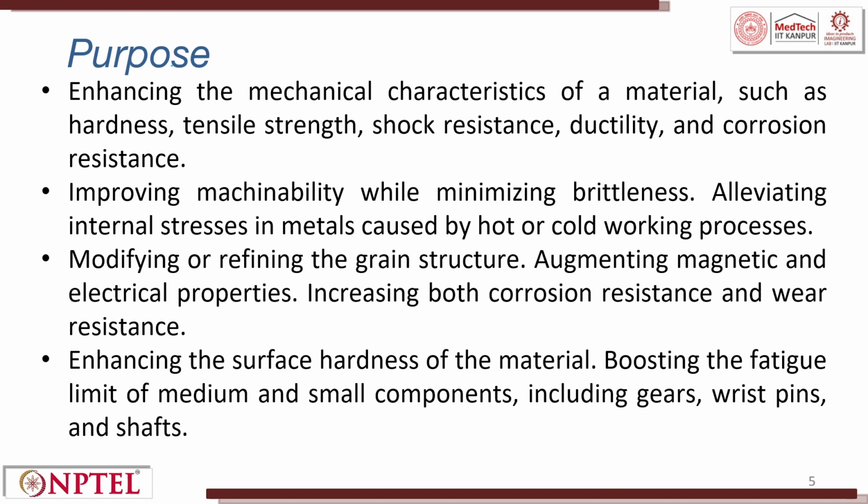So, what is the purpose of heat treatment? It enhances the mechanical characteristics of a material such that its hardness, tensile strength, shock resistance, ductility and corrosion resistance improve. So, if you want to enhance any of these properties, you can play with heat treatment. Improving machinability while minimizing the brittleness, eliminating internal stresses in metals caused by hot and cold working processes.